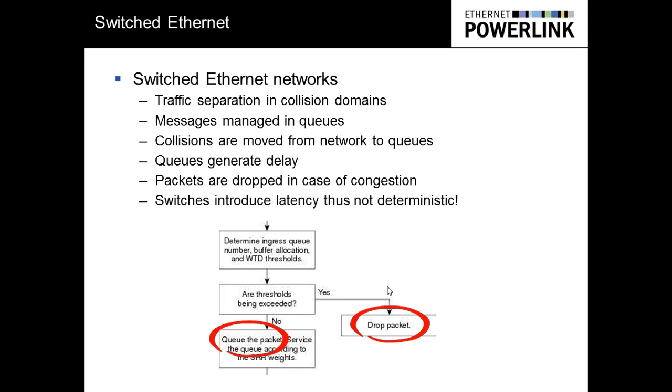And then if there are some communications that happen that are unaccounted for, you're going to end up with queues. And if you run out of queue length, your packets are going to get dropped, and then you're going to have to go back and retransmit again. Plus, queues also mean that you're going to have a non-deterministic amount of delay, and again, it depends on the length of the queue. There are many systems out there that are using switched Ethernet today, but switches introduce delays, and they're also quite expensive. So ideally, we would like to have a real-time network that is not dependent on switches.